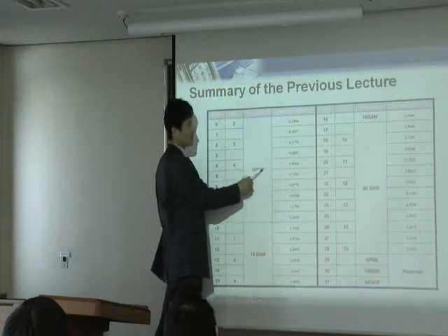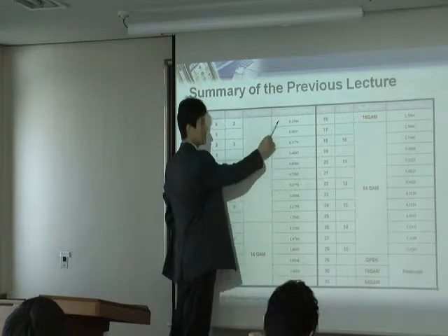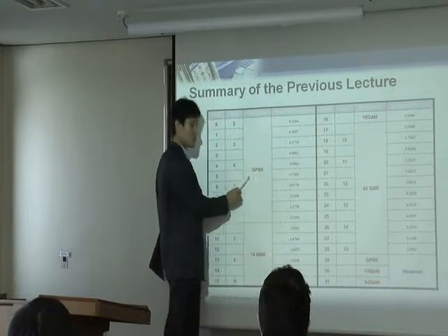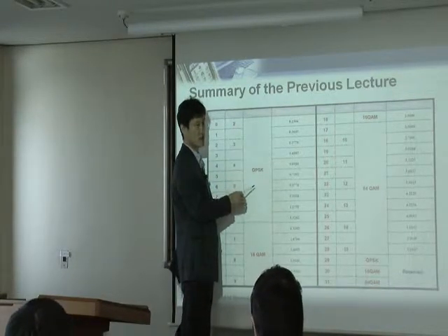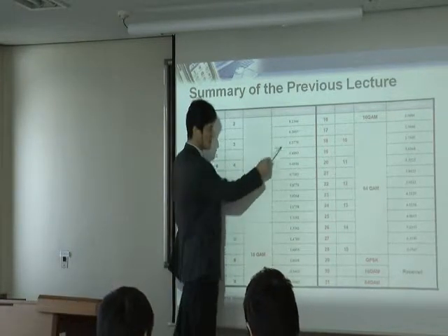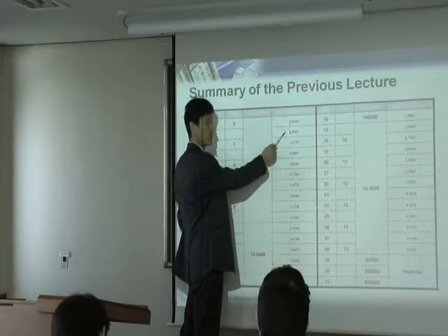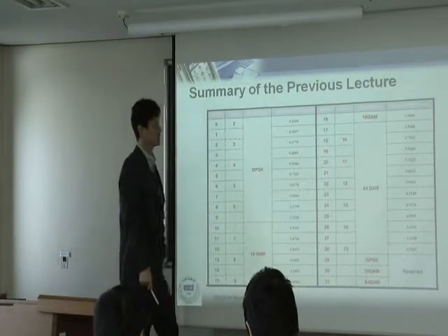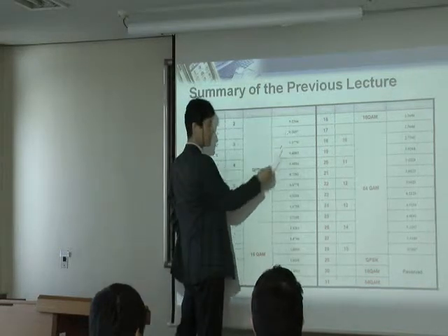Modulation QPSK with some code rate, then you combine these two, and you achieve this spectral efficiency. Then using the same QPSK, (LTE does not use BPSK, they only have QPSK; they consider 3 different modulations) in this case they use QPSK with another coding rate, a higher code rate, and you get a spectral efficiency like this.